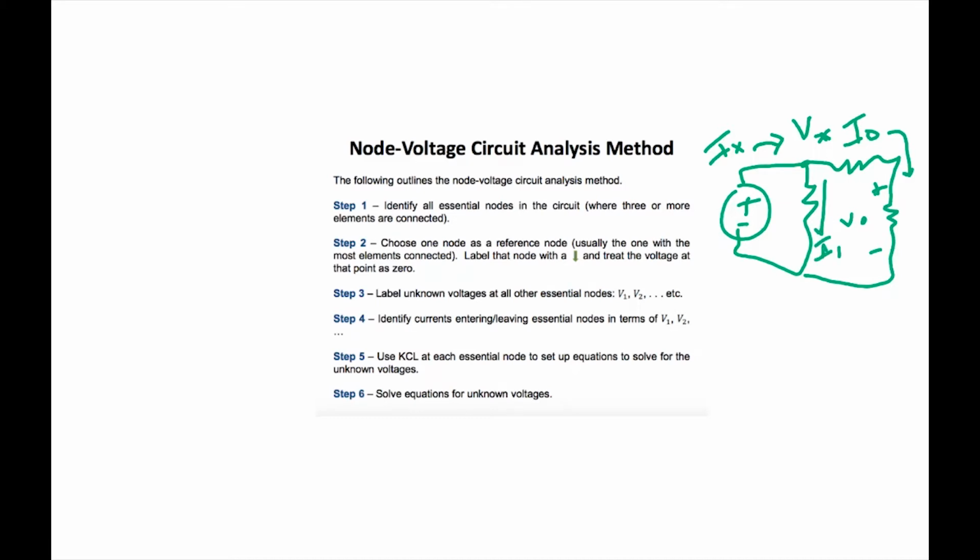That's how we know where current is coming in and where current is flowing out, and that is basically the basics to setting up KCL. We can then solve the KCL by setting up the equations, like V is equal to IR for almost all these nodes, and usually node voltage is the best strategy for solving a circuit.